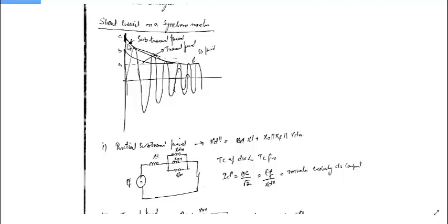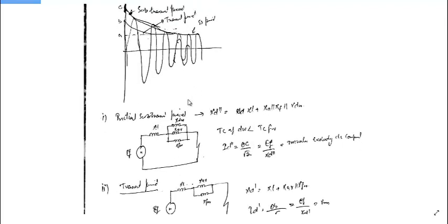So after completely decaying the damper winding, there will be the transient which will flow through the field winding. They will continue to flow, and after the flux has sustained its value, you will see that the current through the field winding will also reduce to zero, and finally the normal current will flow through the system, and that normal current will result in the normal flux of the system.